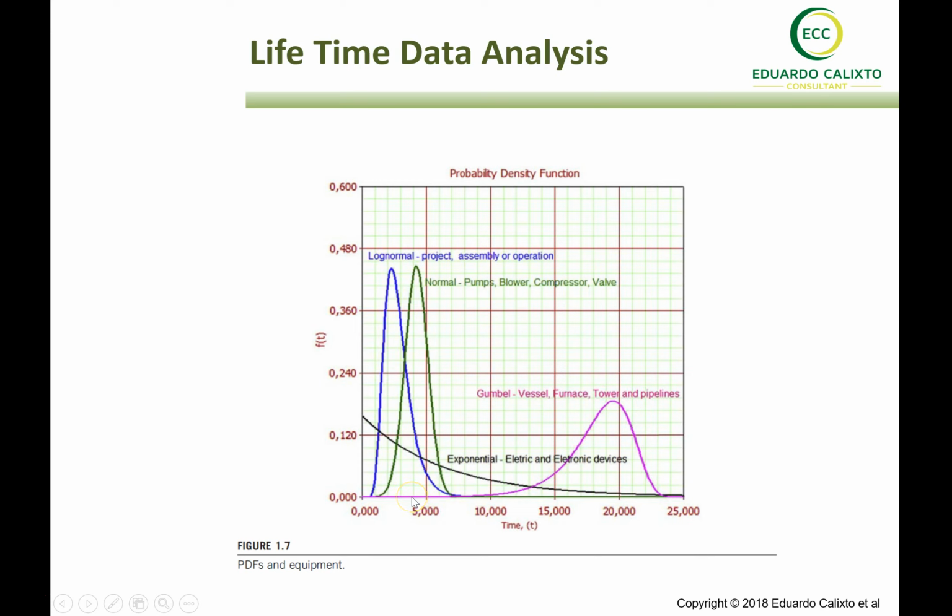That can be a fit for a lot of rotating equipment such as pumps, blowers, compressors, or even valves. If you plot the failure rate here, you have an increased failure rate after some specific period of time, and of course you need to perform some preventive maintenance to detect and avoid such failures.